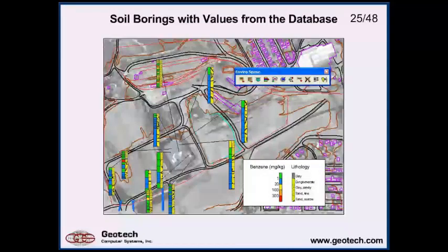Here's another one where we've stored some geology in the database, and we're making these stick logs. One track is the concentration, and the other track is the lithology. And we did a project where they figured out that the concentration of the rad material was in the fines, not surprisingly, in the clays and the silts. So they bought industrial log washers and washed it off. It was in glacial till. The boulders, cobbles, and pebbles and all that went back in to backfill, and the silts and clays went in the rail cars off to Utah. So these things can be really useful at times.